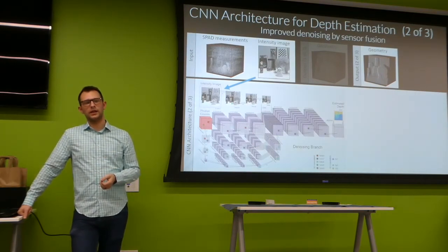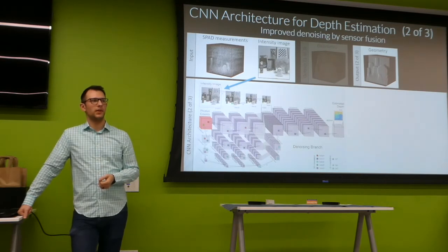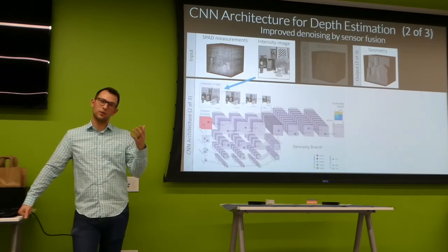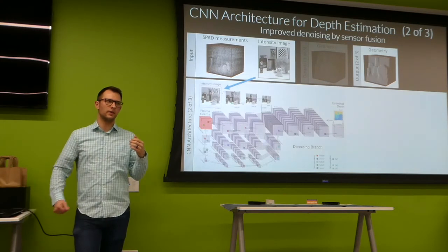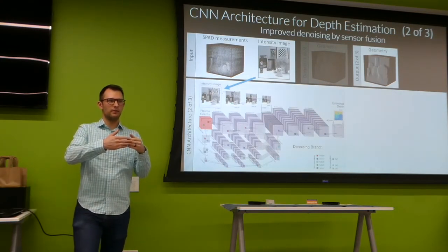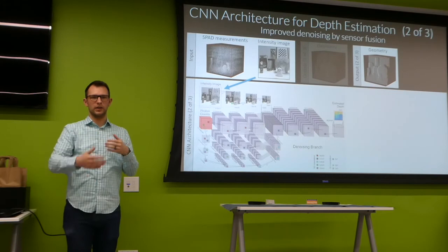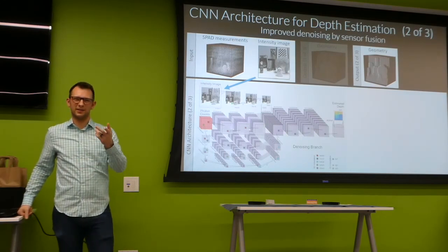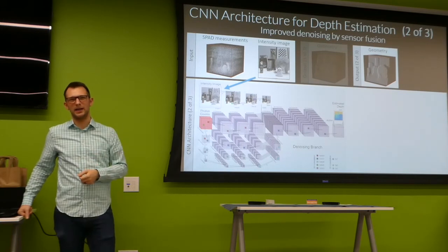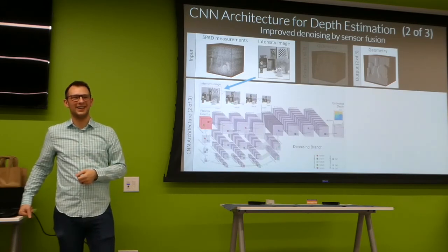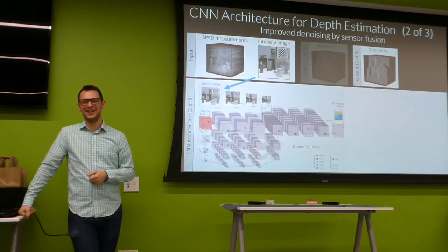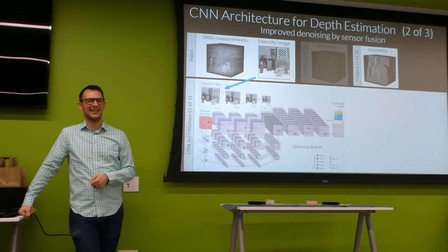Yeah, so can you use existing systems to do this? We played around with this Velodyne LIDAR for a while, but the challenge was that we didn't have access to the raw data, which we really needed. So they primarily give you just the first return. There's a dual return mode, which I think is typically for a situation in which you have maybe a glass or something, where you can get that second return. But for us, we wanted the raw data. We haven't been able to get that yet. But if you know of... I was going to say, Velodyne's not very far away, so you probably could... Yeah, if you can convince them to give us the raw data.